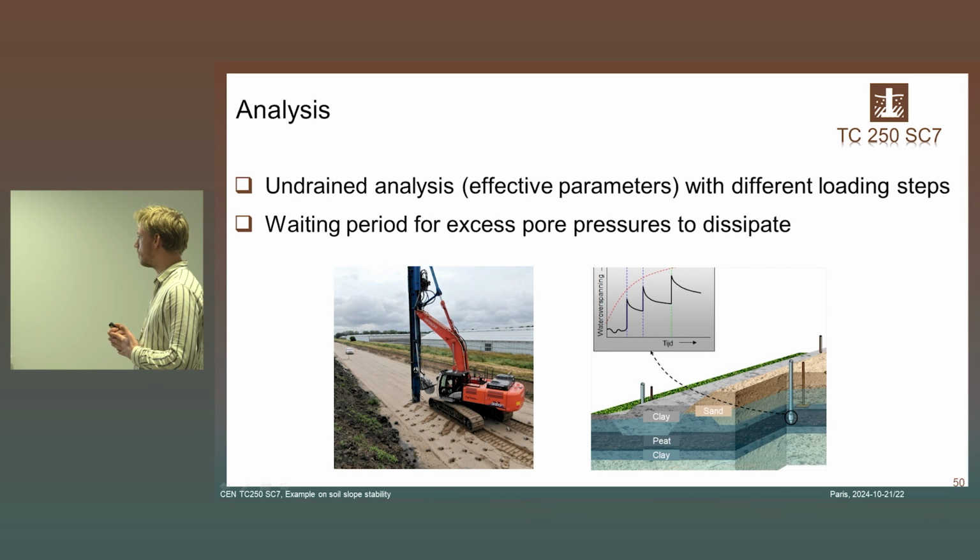I think this is the most important part in the analysis for slope stability for infrastructure in the Netherlands. Almost always preloading with sand is used to meet settlement requirements in the Netherlands, which are often 5, 10 or 20 centimeters during an operational lifetime of the highway of 20 years.